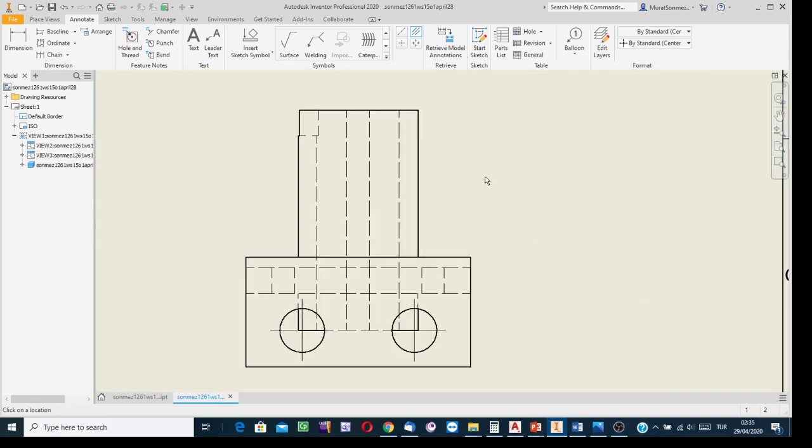And on the left side view, yes, for this cylinder, indicate the limiting lines and have the longitudinal axis. Instead of indicating this and that, I clicked the escape button and I'm going to use the stretch technique. Yes, I extended the line using the gripping method.